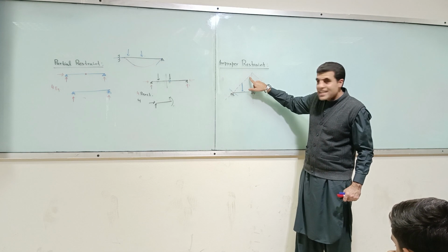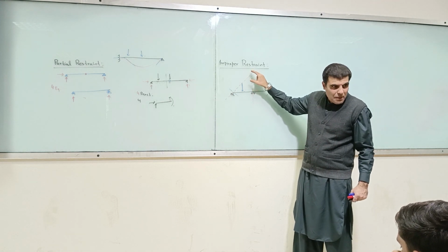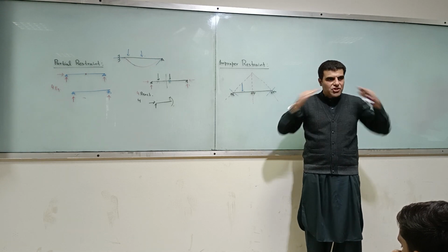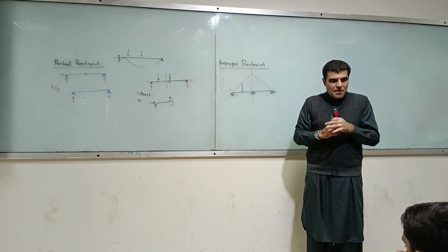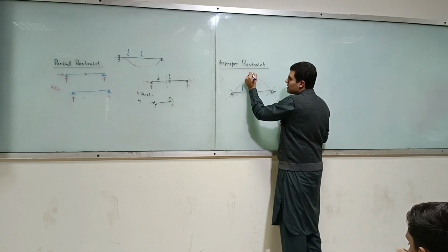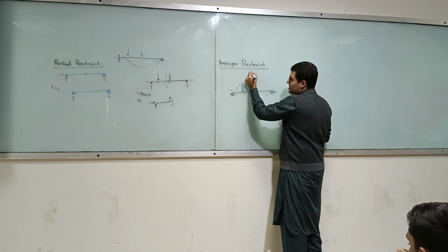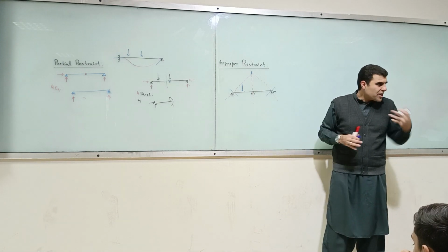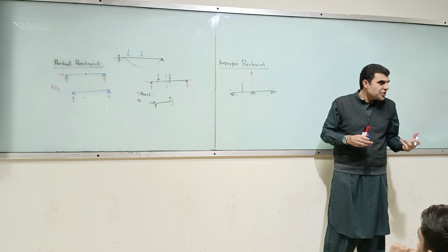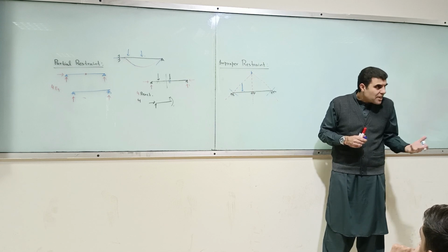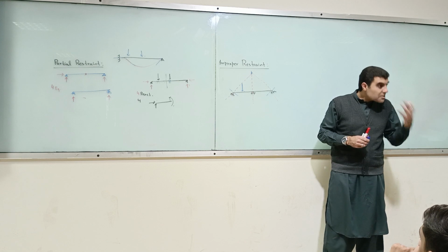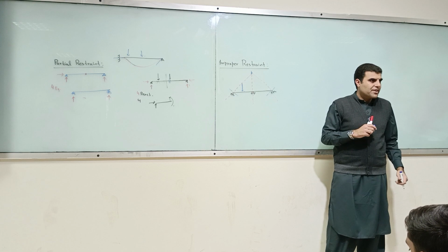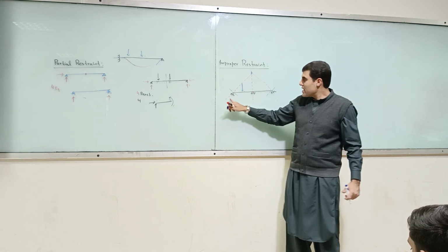Because there is no resultant force which will cause moment about this. All the reactions are merging at one point, so whatever resultant you have will have zero lever arm. So that means your reactions won't satisfy which equation? The moment equation. So you must make sure that all your supports don't meet at the same point. You should never have this thing.